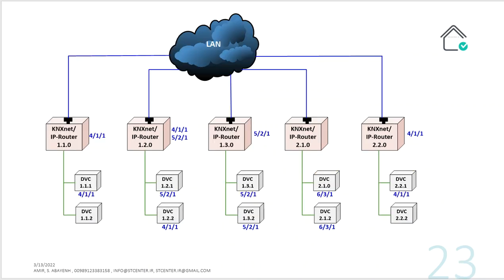The recommended setting by KNX is to replace all line couplers with IP routers. In this case, we do not have a backbone coupler anymore. They have vanished, okay? But we have the different areas and different lines. And how do we make the difference? By assigning the right physical address. So the IP router in line 1 area 1, the physical address is 110, and the IP router in line 2 area 2 is 220. Okay, great.